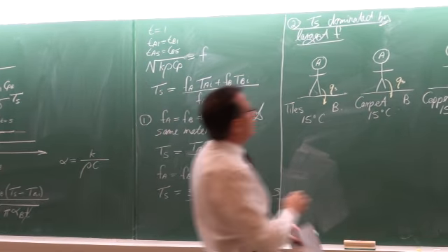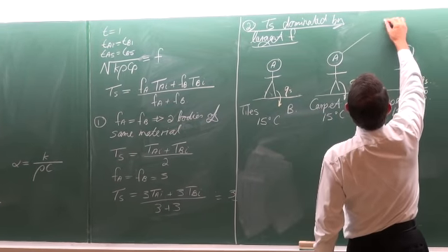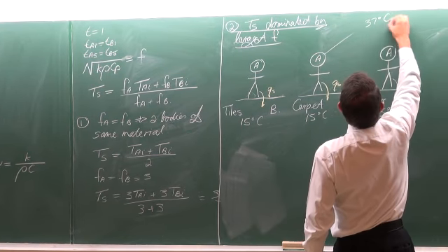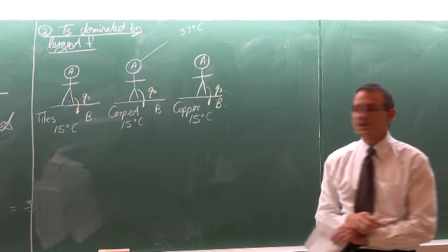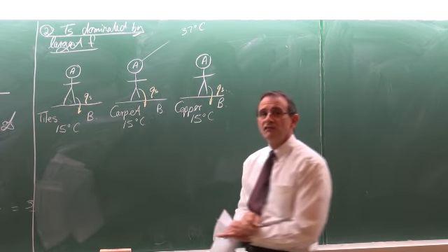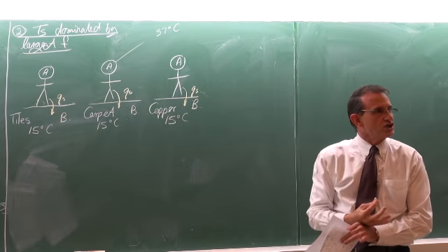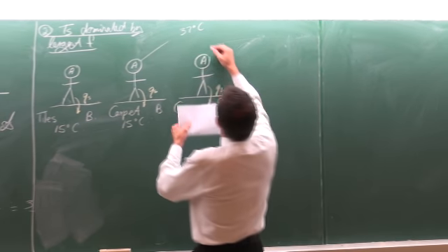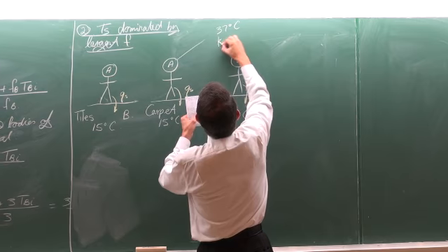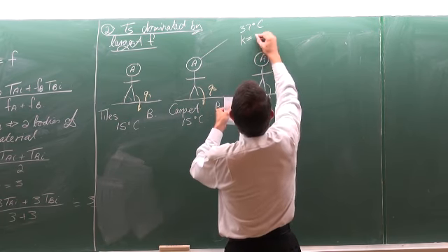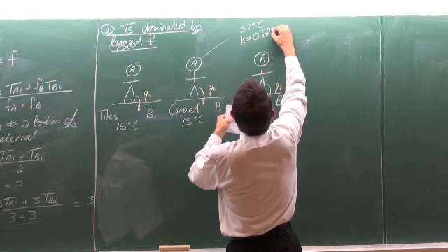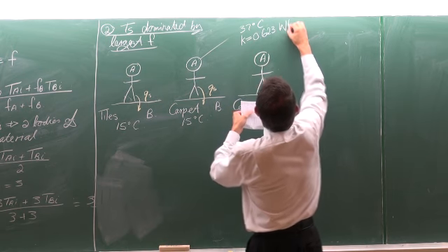Okay. Now, you're this human being, so if you're not sick, your temperature should be 37 degrees Celsius. We know that 72% of your body is water, so we've done it previously where we've determined the thermal conductivity, which is equal to 0.623 watts per meter Kelvin.